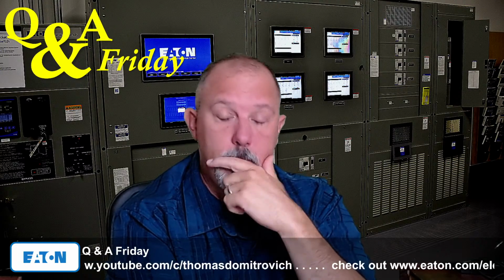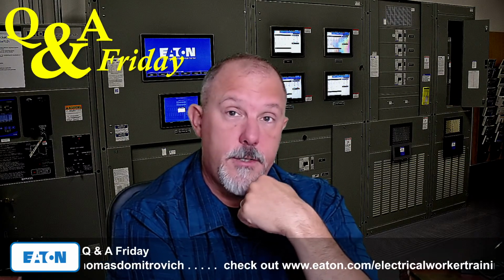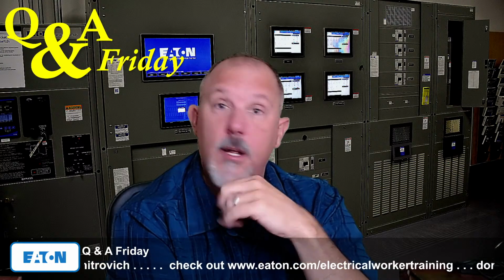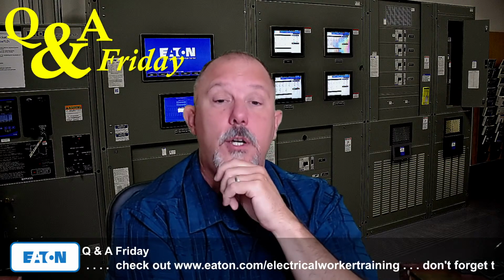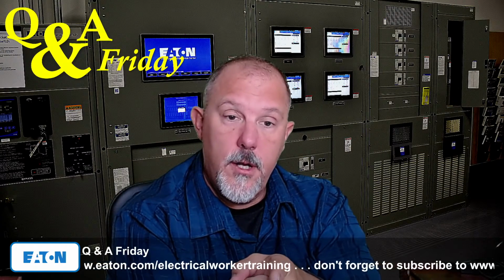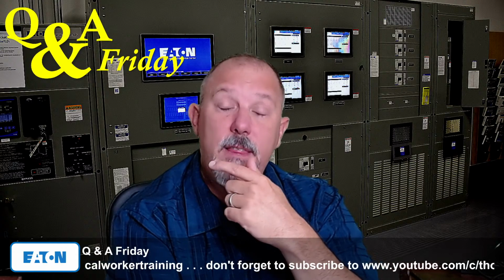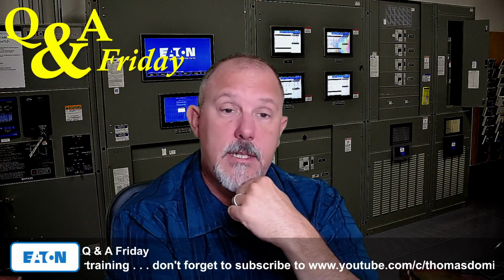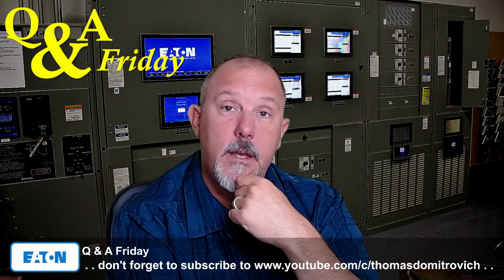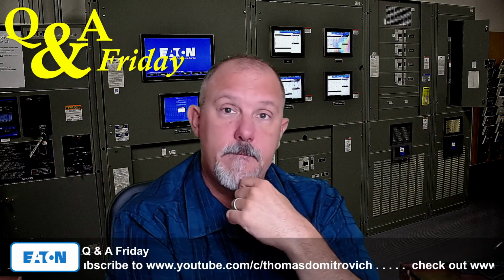And I would argue that you'll want a minimum arcing current that you need to consider, but we don't say that anywhere in the code. I don't necessarily disagree with you about arcing current examples in the annex, but I think the first thing we really need to do in the NEC is define what the arcing current is, and what your references are to calculate it.